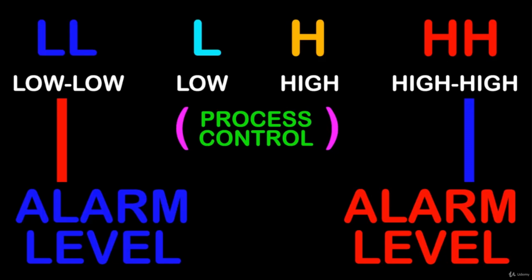So imagine, if you will, we have a temperature. We have an input coming in as a thermocouple, and we have an output going out to a heater. And this heater isn't controlled by a thermostat. It doesn't have variable heat. This heater is either on or it's off. And the way that we'll control this heater, we're looking at an analog signal from a thermocouple that's telling us what our temperature is. And let's imagine we have it scaled from 0 to 100 degrees.